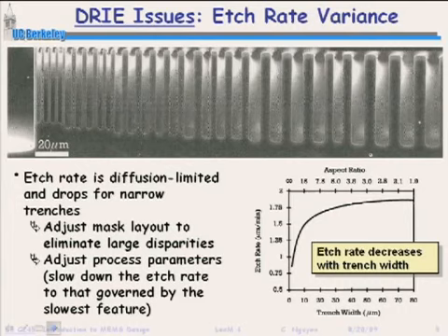Right? The amount of material you have to etch will change the etch rate quite a bit. And you can see even here, just the sizes of the openings changes the etch rate. So this is not an unusual thing. This happens with almost everything. And that's why in the lab, don't trust anyone's etch rate. Always determine it for yourself using your mask.